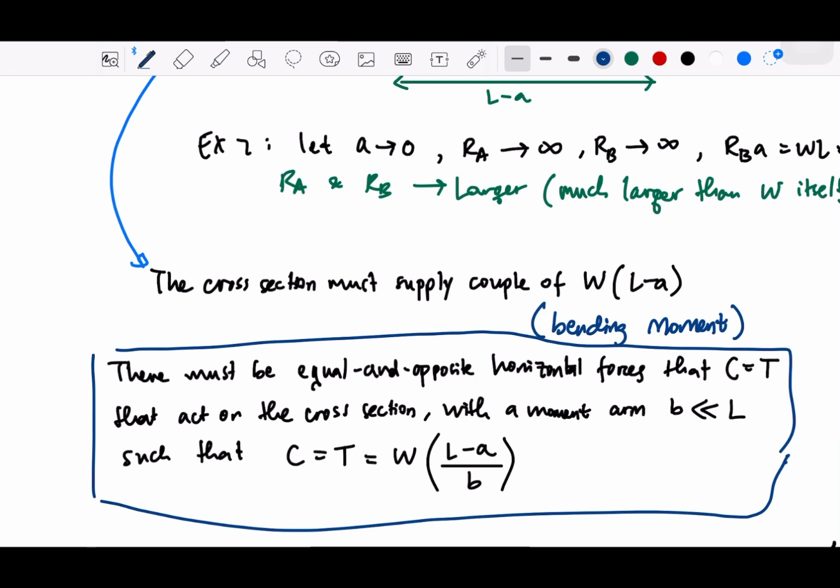So you can imagine if you want to design something simple for farmers, like a shovel, how large the handle distance will be. If the handle is too small and the farmer doesn't put enough distance between the hands, it's not efficient and the shovel can break, which means it breaks on its bending side. So that's the bending moment that makes the shovel break.